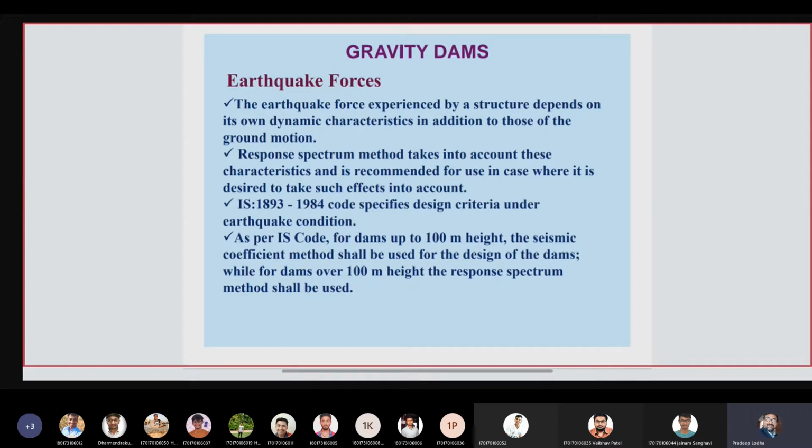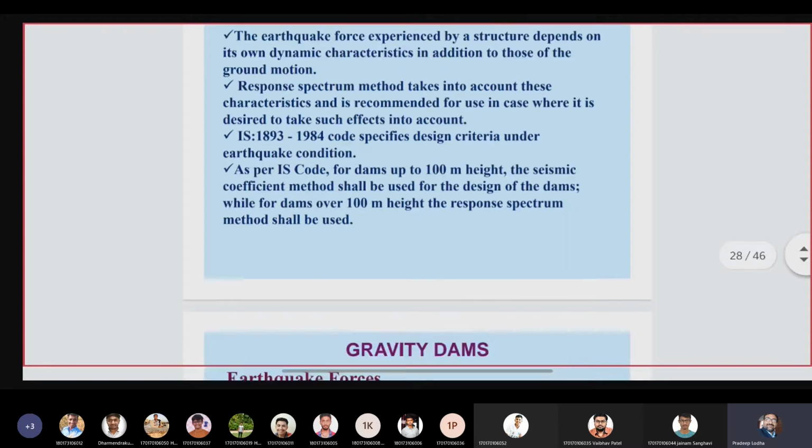So it is a much less demanding, less challenging method of design for considering the earthquake forces, as compared to the response spectra of the structure. If we consider that, then we also have to calculate T, the period of the structure. So there are two methods. Here I would again like to mention that in both methods we are mostly interested in the horizontal coefficient of acceleration being imparted to the foundation, which would be detrimental to the design. So I'm taking you to the next slide and will explain how it affects.